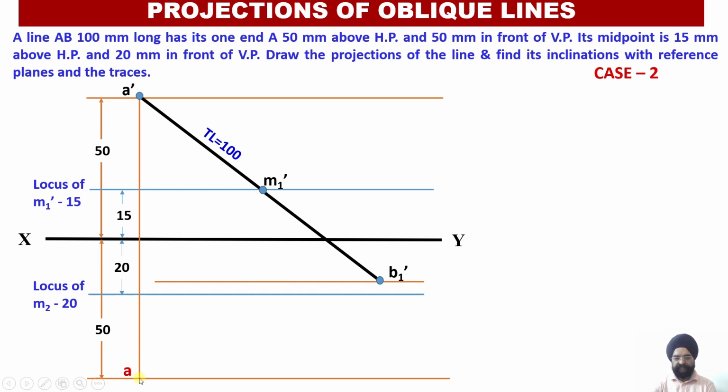So please check, this is my coordinate location, that is the starting point. I'll open my compass 50 millimeter because the true length is 100 once again. Again extend this 50 by another 50, so this 50 plus this 50 makes it 100. The moment I obtain the second point of the true length, which is 100 millimeter, again I'll draw a long locus line over here using a 2H pencil.